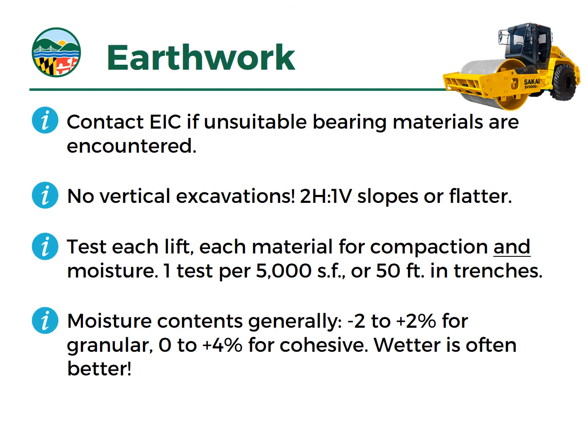Wetter is often better is a phrase we've heard a lot, and particularly for cohesive materials, because you get less permeability, a more elastic soil, less prone to brittle deformations and cracking. And it can be too wet, though. Too wet, especially in a very sensitive, cohesive soil, can just lead to pumping and rutting and generally bad compaction.